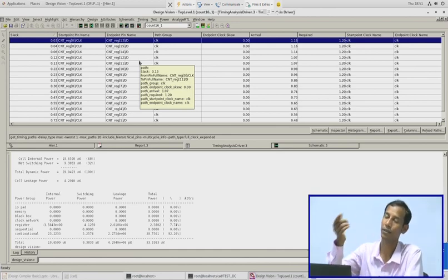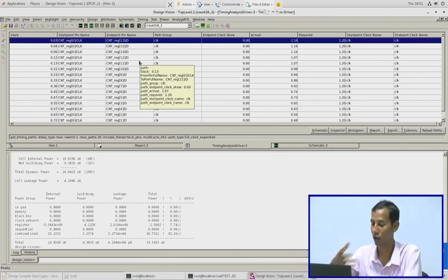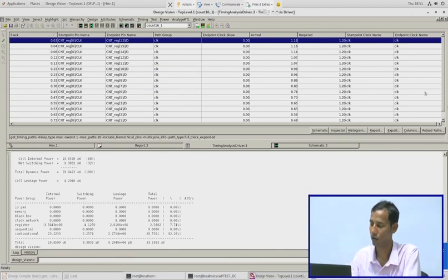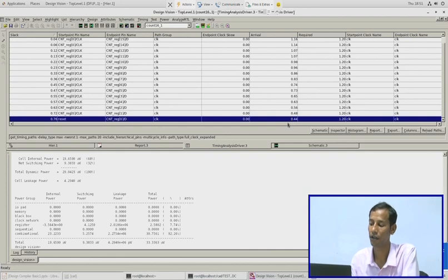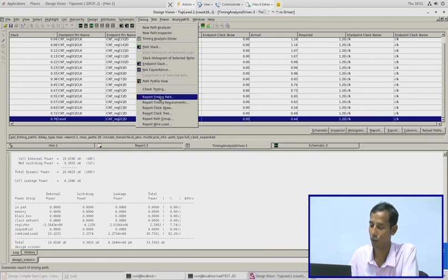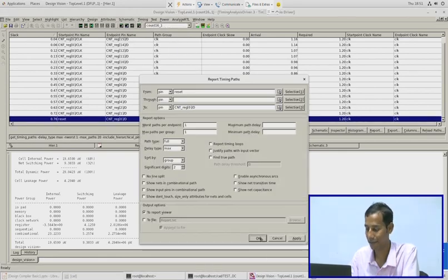But on the MSB side, as that is not at all connected with the logic, that means any logical gates, they are taking less time, even that is 0.44. Then again I have to check the timing information, whether the slack is met or not.